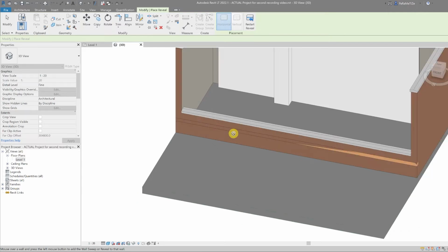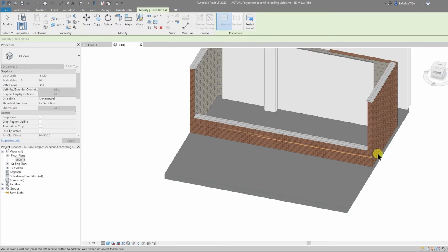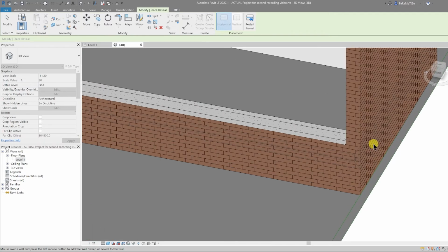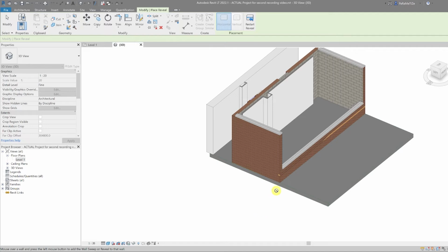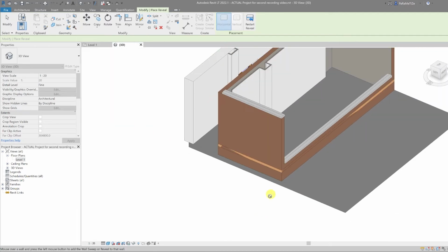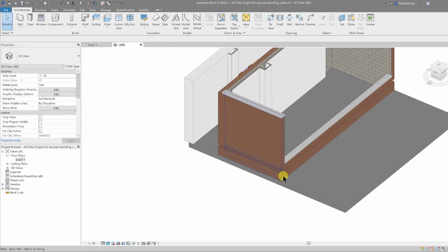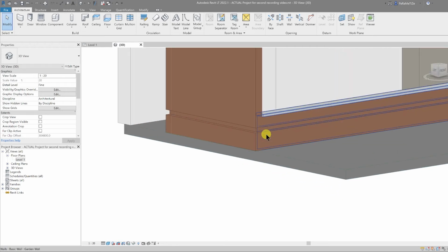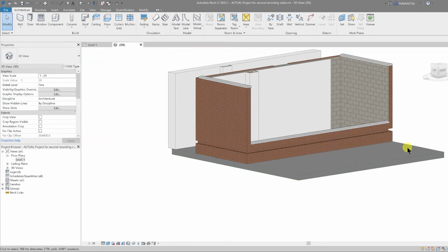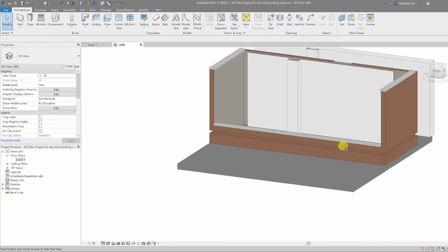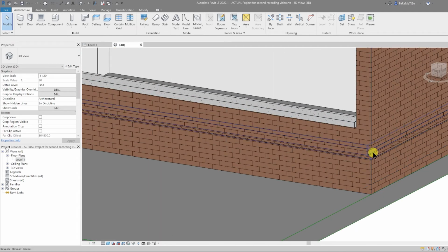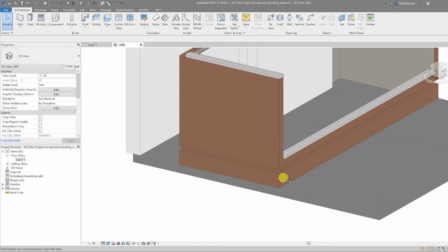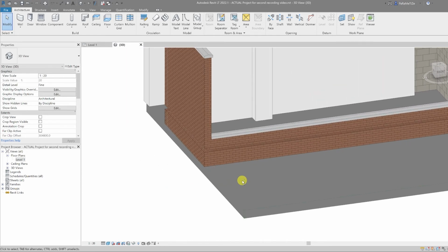So I click on one wall and that reveals in place. If you continue clicking, for example, this wall that goes at a perpendicular angle, this will continue that reveal around each wall. So we can press escape out of that, and then we have our reveal in place. Now the reality is that no reveal will be that big for such a thin wall, because the wall will shear, it will break, and it will collapse. So let's do a more appropriate reveal by changing the profile.